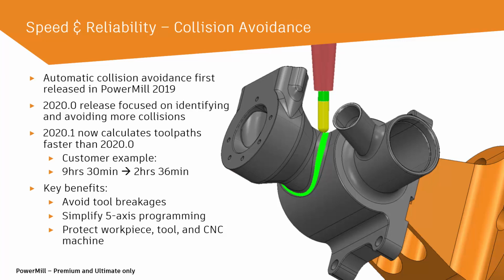And the key thing here is that the automatic option works regardless of the toolpath type being calculated or indeed the shape of the model that's being machined. That's a major bonus there in terms of Powermill's usability. Now, this ultimately helps programmers to produce safe, predictable and smooth 5-axis tool motion that's going to allow them to cut their parts.